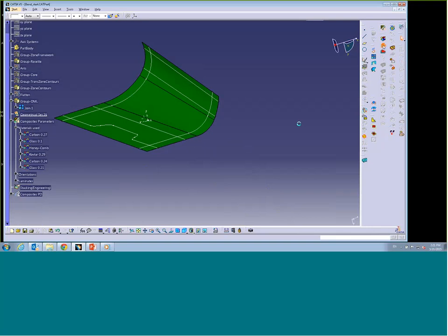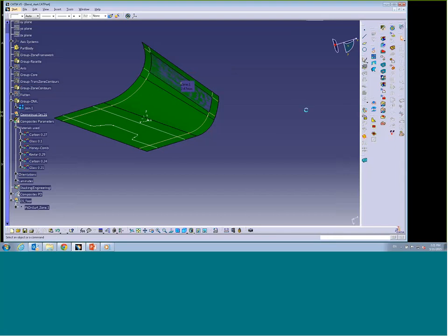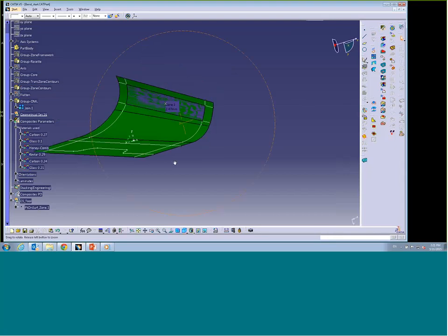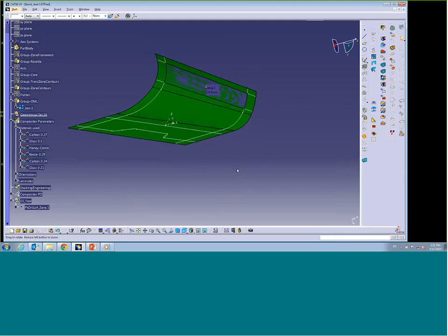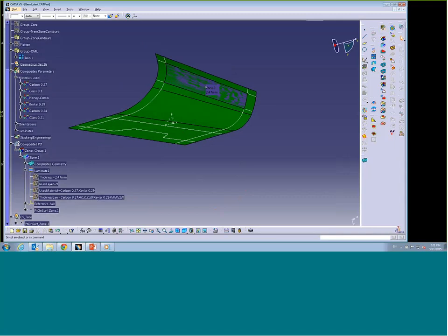So my first zone is going to be the thicker one. So that's going to be from here to here. What's a laminate? So right now I have 3 laminates in the model. The thickest one is laminate 1. Just put it in. Rosette, it automatically takes it from the group and just hit OK. So what I ended up with, as you see, created a zone. I created a new entity in the specification tree. It says zones group, and that's zone 1.